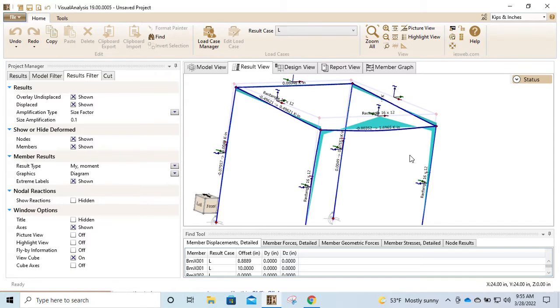When we do this in VA, or in finite elements, we have linear displacement, which means we have constant strain, which, as we remember, if I drew that little free body diagram, we don't have equilibrium along the length. In order to get that, once we know nodal values, we can use mechanics and get our own expression for the axial load, the shear, and the moment within the member. What does mechanics mean? Draw free body diagram.